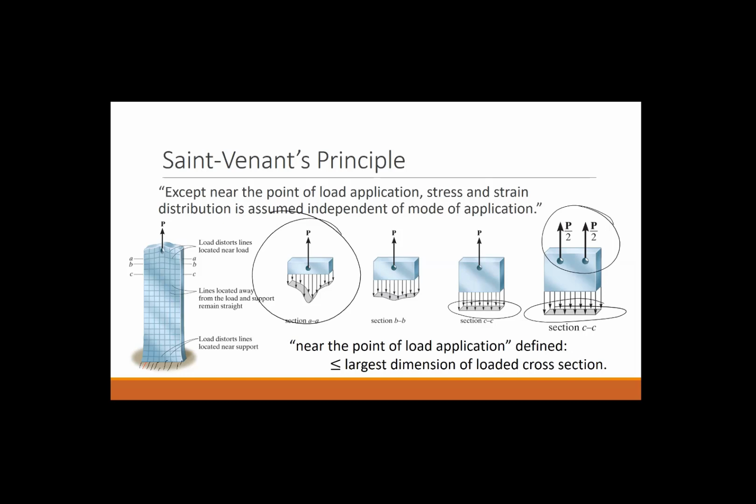If you want to know the stress state right up around the load application, that's a much more complex question. Typically we solve for that using some type of software where we model it and do a finite element analysis and see how the stress distribution changes throughout the cross-section. But if we're designing far enough away from that, then it doesn't really matter how we say the load is applied. We can apply it in the easiest way for us, because it's going to end up being more or less this uniform stress state or some type of predictable stress state, as long as we have the same moment and same sum of forces.